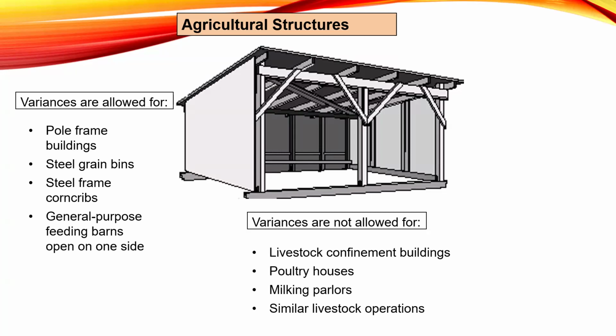And so then no human habitation or occupancy, of course, single wall design. Again, no retail, wholesale, or manufacturing type of uses. And it's going to have to meet those requirements that I mentioned earlier that are listed out in the model ordinances that we have, and also have that floodplain development permit issued.